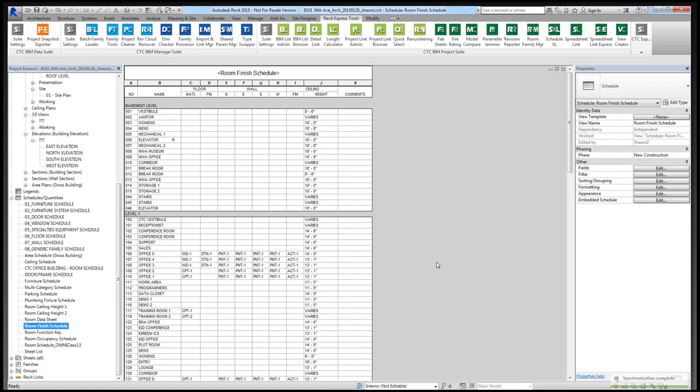So I ended up having to fall back on using the bounding box and the insertion point, and I could find the upper limit of Z, and I could find the placement elevation of Z, and I could do some subtraction there.